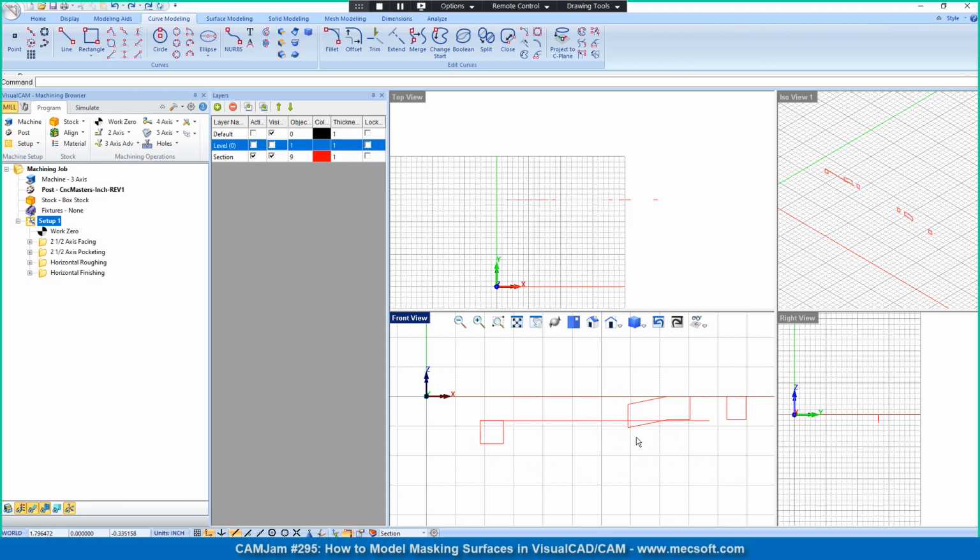What I want to do is, when you cut a section, the curves are joined, they're merged together. So what we want to do is explode those so that we have access just to that line. So now we're going to extend the line: pick extend, pick the line. We're going to extend it all the way down to this line. So now I'm going to trim it. And then also I don't need this anymore.